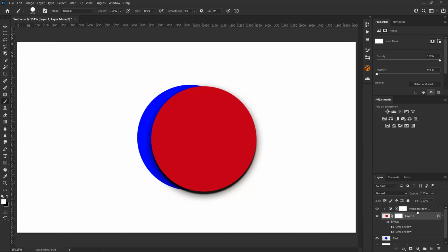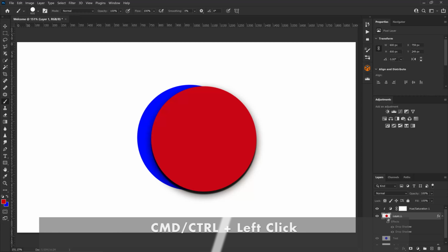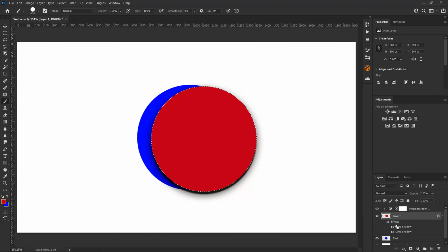Masks are also a great way to keep your details within a selection. If I Control-Command-Click on the layer of the circle, it will be selected. If I click the Add Layer Mask tab to it, you will see the box is mostly black, but white where the circle was selected. Now if we paint on this layer, only inside the circle will we see that's painted. Even if we go outside the circle, nothing will be painted because the black portion of the mask is hiding it.